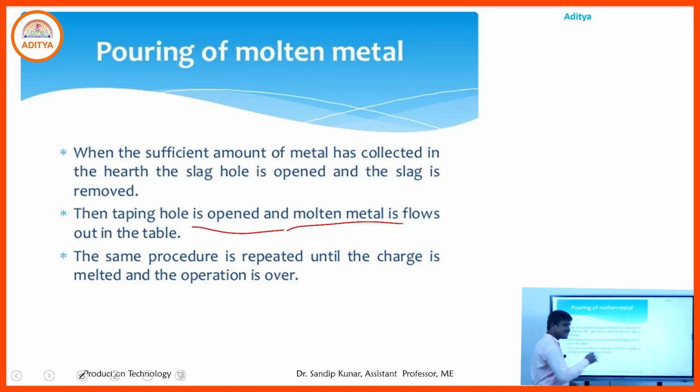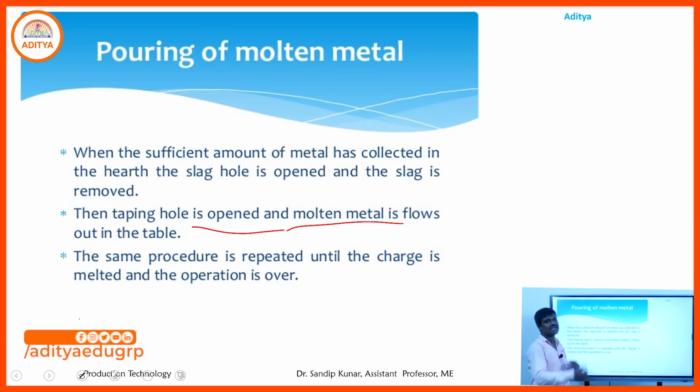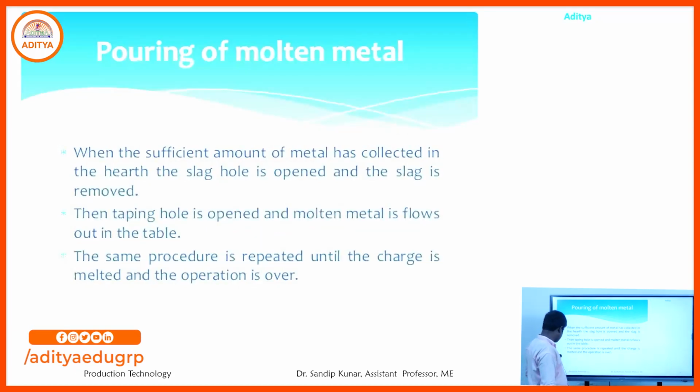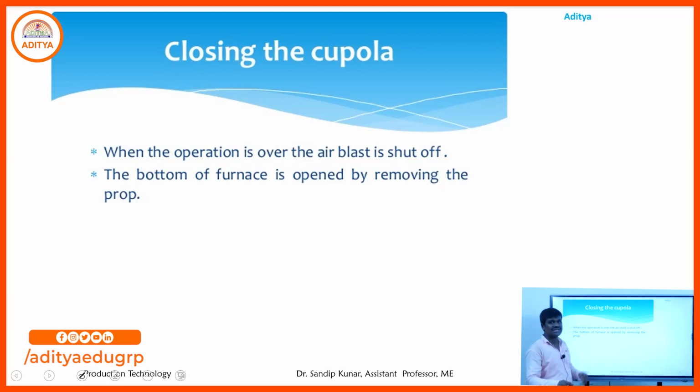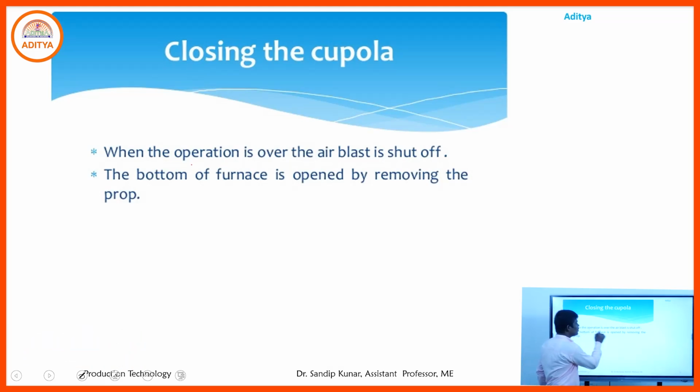Then the same procedure is repeated until the charge is melted and the operation is over. Up to that time we repeat that procedure. When closing the cupola, once the operation is over, the air blast will be shut off, meaning we do not send any extra oxygen.